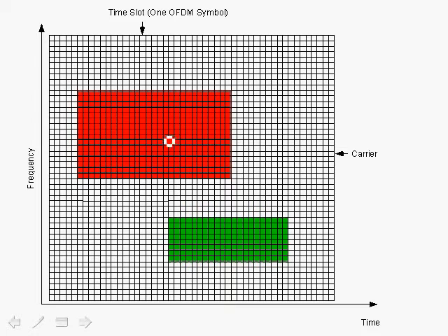For example, subscriber 1 here and subscriber 2 here. So in an uplink from the subscribers to the base station, we can also use OFDM multiple access as shown over here. Now again, I'd like to emphasize that I have simplified the picture considerably, ignoring, for example, forward error correction coding and assuming that each carrier has, for example, 6 bits per carrier for 64 QAM.